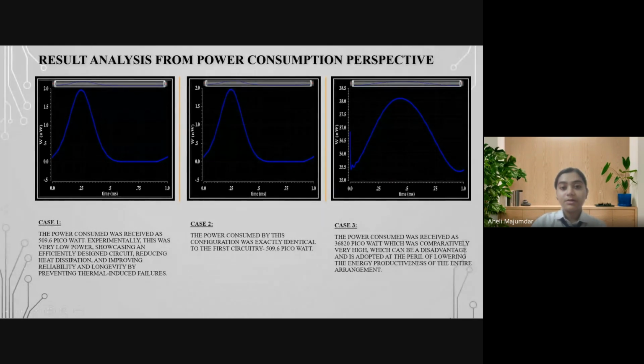The reason for this was that for the unity gain buffer circuit, the reduced voltage led the circuit to draw maximum current, therefore maximum power was consumed. But this was not the case for the first 2 configurations because they had 2 input pins, and the total current in the circuit was the sum of the currents individually through the 2 transistors.